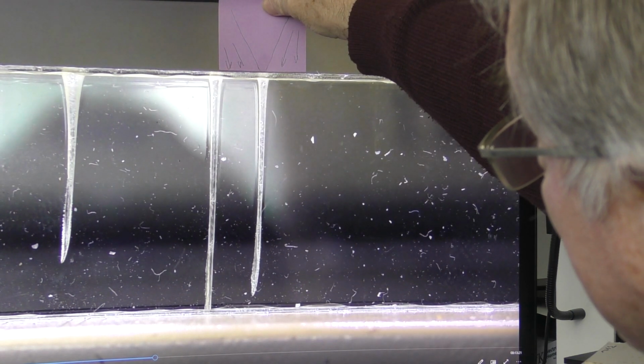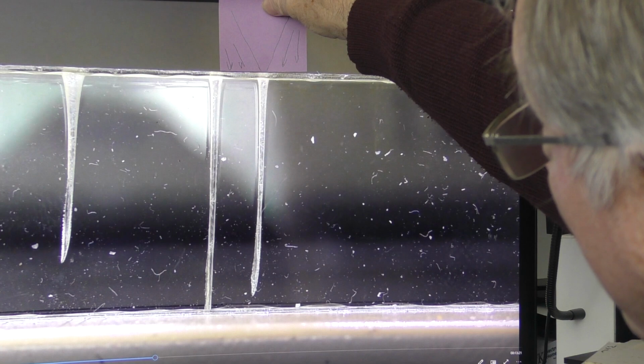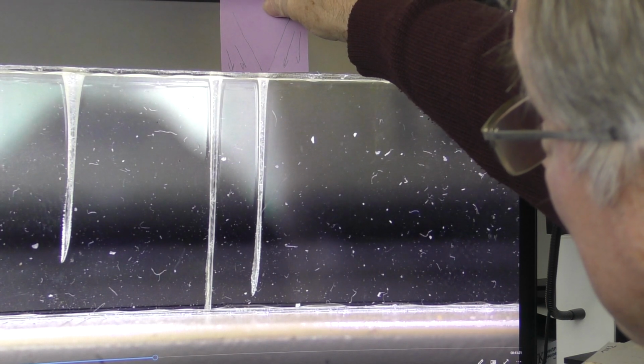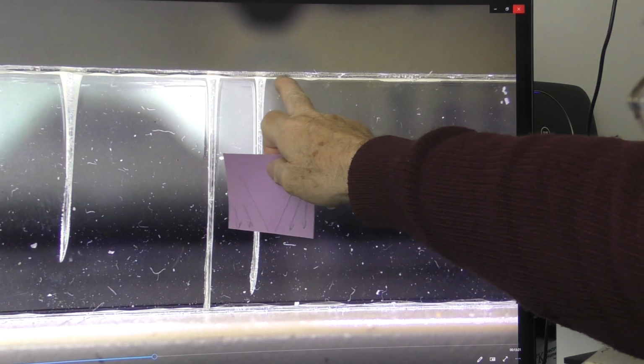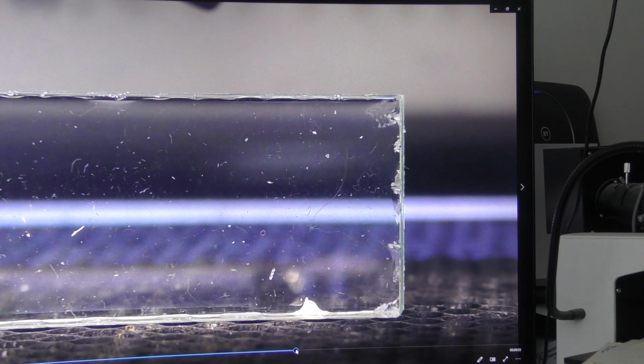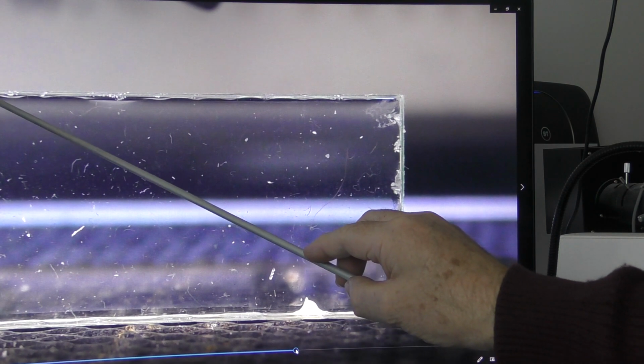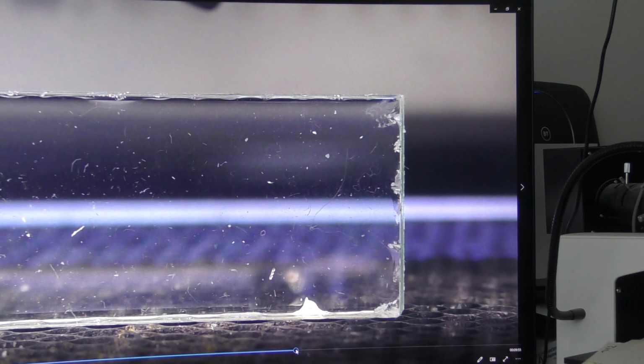Any lower intensity beams outside here are not going to add to that hole, that damage. But what they are going to do is, if you take a look around the outside here, you'll see that there is damage on the surface. I now change the lens to a 1-inch focal length lens. And remember, a 1-inch focal length lens has supposedly got a much smaller spot size. In other words, its energy density when it hits the surface of this material is substantially higher than it is for a 7.5-inch lens.